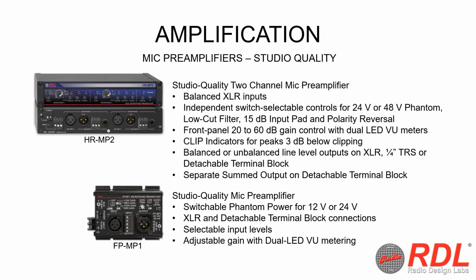It has clip indicators for peaks that are 3 dB below clipping, and the output supports balanced or unbalanced line level out on XLR, 1/4 inch tip ring sleeve, or detachable terminal block. There's also a separate summed output on detachable terminal block.